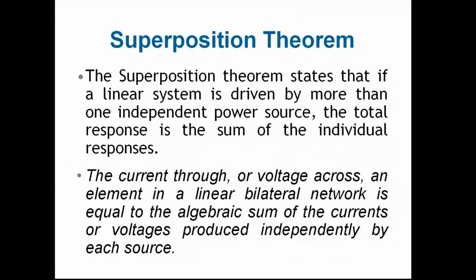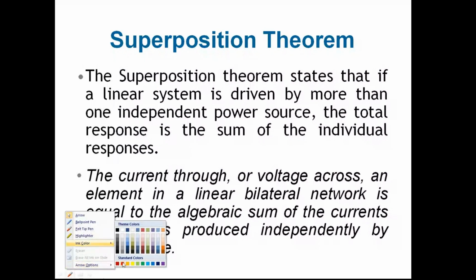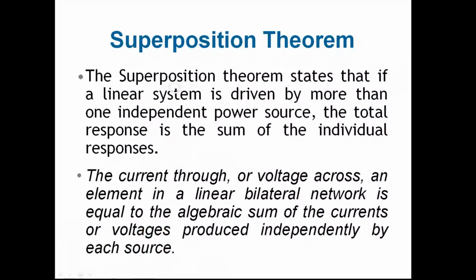Superposition theorem. The superposition theorem states that if a linear system is driven by more than one independent source, so if your circuit contains more than one independent source, then the total response is the sum of the individual responses. This is the statement of your superposition theorem.